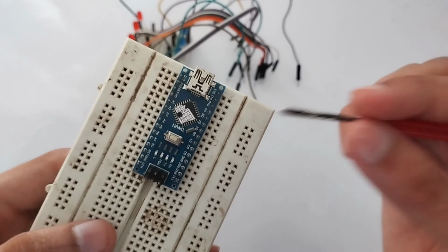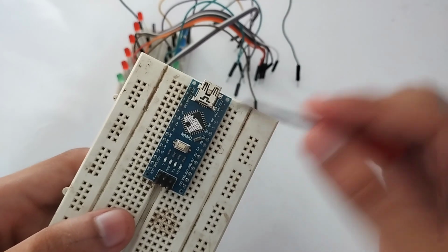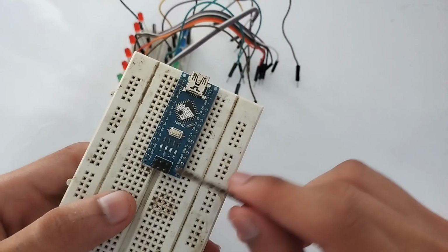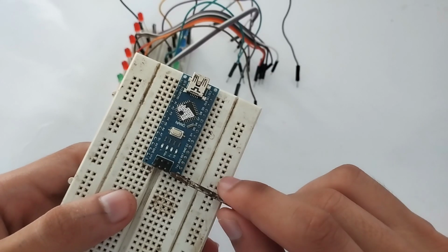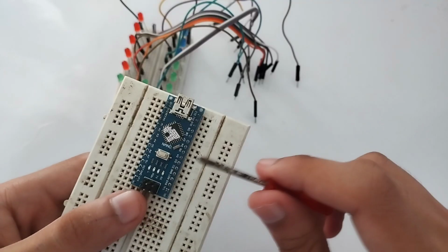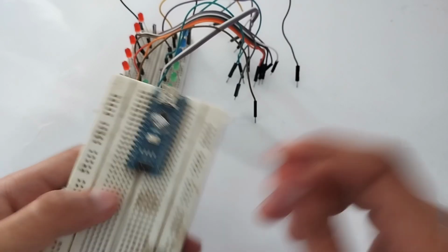You see the Arduino Nano has a total of 14 digital pins, D2, D3, D4 all the way up to D12, and one more pin, D13. So 12 pins are there, and two pins are labeled as TX and RX, right? We can use the TX and RX pins as digital pins also. The problem that I was talking about is related to these TX and RX pins, right?